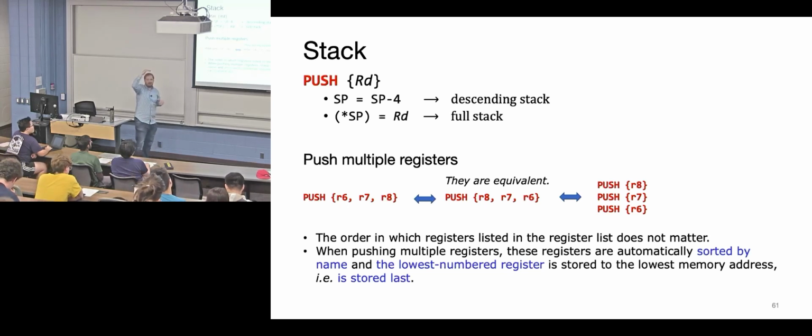The stack's at the top of memory. If you remember your memory layout, there's a bunch of reserved space up there for ARM to have control of registers, or memory space. You're just below that, but technically you're at the top of the most available memory. So you're going to put your data there, and then it's going to descend down the stack. So you're always moving down.